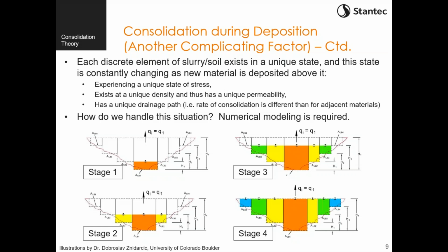There's a few codes that are dedicated to do exactly this one-dimensional consolidation modeling. Examples would be FS Console and Condis, and we typically use Condis. We found that it tends to be more accurate. And now there's also the ability to do things like a three-dimensional Plaxis model or a three-dimensional FLAC model. That can certainly be done in situations where the three-dimensional effects are significant. But for most of our calculation purposes, and really with the end goal of the water balance in mind, this tends to be perfectly adequate. We don't need to go into any more detail than this.